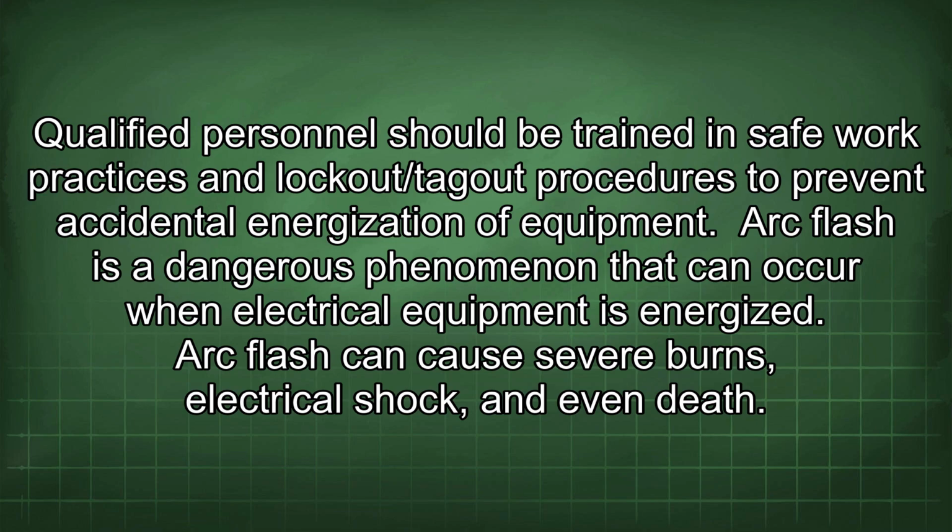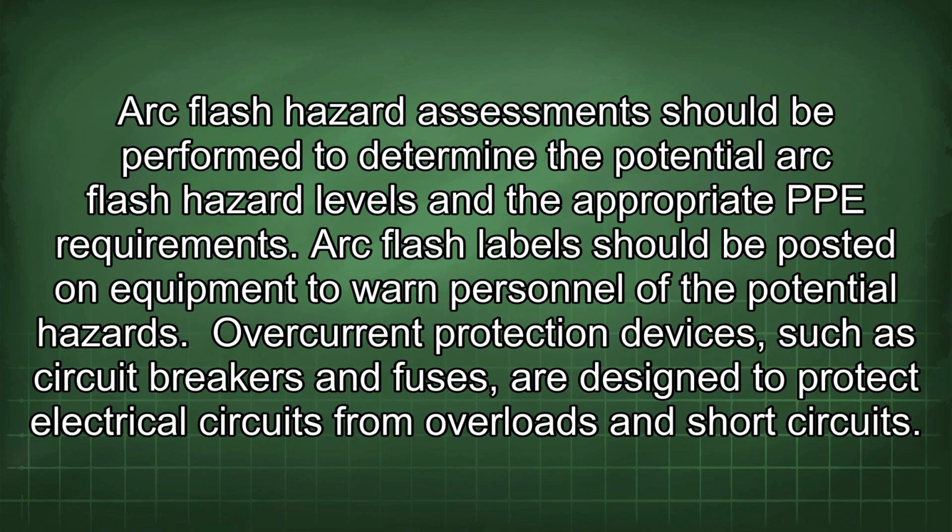Arc flash is a dangerous phenomenon that can occur when electrical equipment is energized. Arc flash can cause severe burns, electrical shock, and even death. Arc flash hazard assessment should be performed to determine the potential arc flash hazard levels and the appropriate PPE requirements. Arc flash labels should be posted on equipment to warn personnel of the potential hazards.